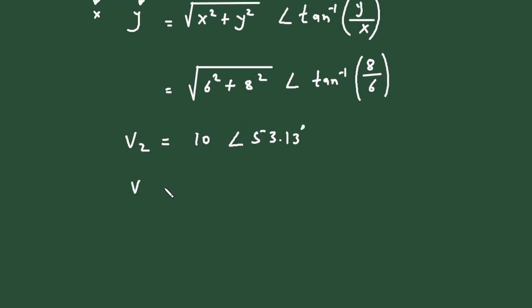If we compare this with standard equation, it will be V is equal to Vm at an angle phi. This is the frequency domain, and small v is equal to Vm cos(omega t plus phi). This is the time domain format.